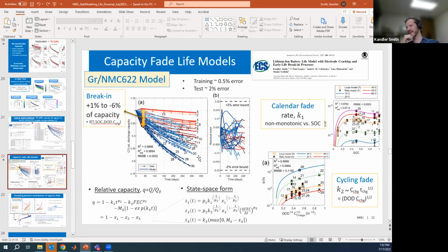We need better ways to interrogate and understand why the electrolyte is breaking down and track it, because electrolyte drying out, turning to gas, or even leaking from the cell is one of those reasons for rapid capacity fade as well as rapid resistance growth.